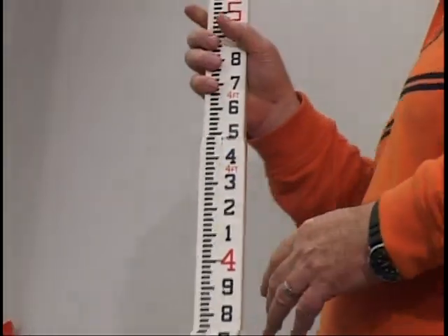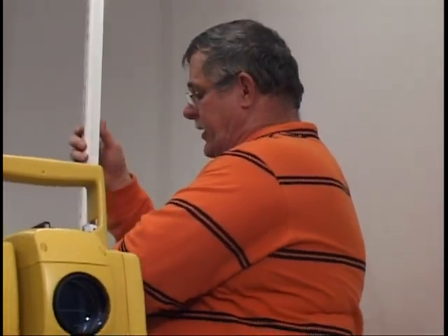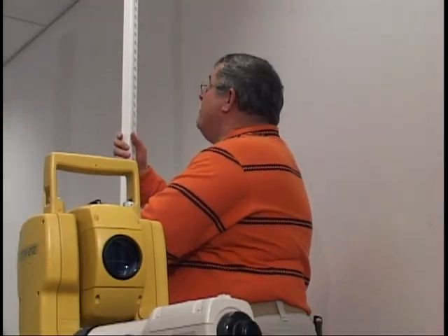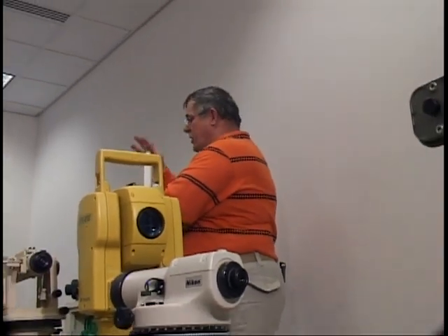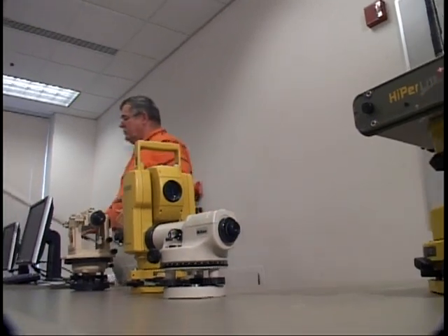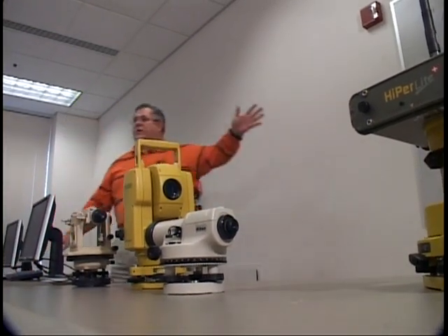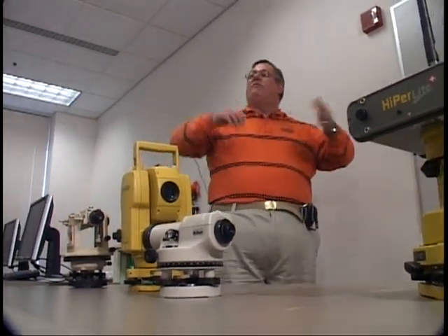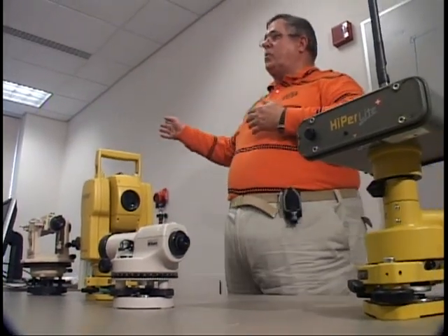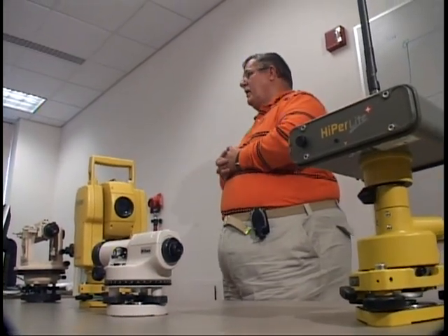And when you're doing levels or measuring levels, and that's one of the things we're going to be learning in this class, how to do differential leveling, we're going to set up midway between 2 points, and we'll take our measurements. Backsight to the benchmark, foresight to the new position where we want to determine what the elevation is.